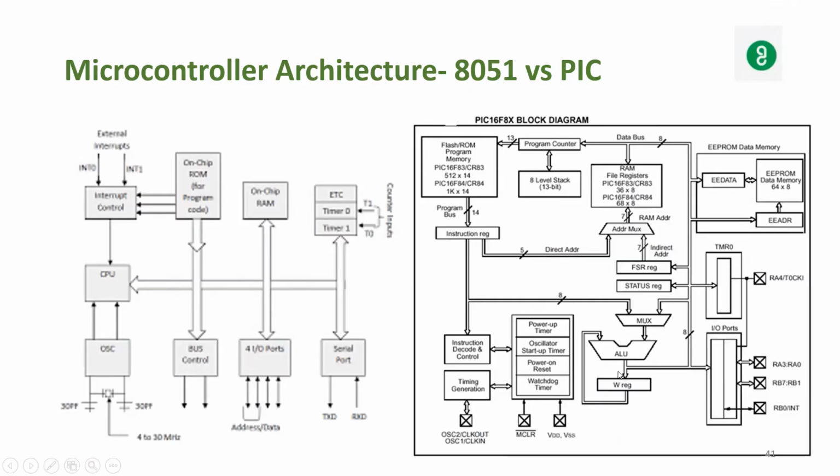And you take the data from RAM. Or whatever instruction that it has to execute, it takes from the instruction register. Both are fed to the multiplexer. It is a 2x1 multiplexer. What it takes is the instruction register as well as the data as an input, and it feeds to the ALU.